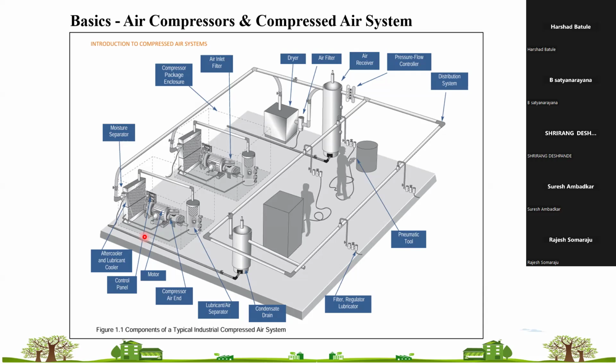Then there is a second stage to evaluate the compressor, which is called the leakage test of the compressor. Let's assume the same system, where we have isolated the valve from the air receiver. Now, if we open that valve and allow the air to pass to the various distribution systems, users can use the air. And what are leakages in a compressed air system? Leakages are misuse, or we can say drain points of our energy.